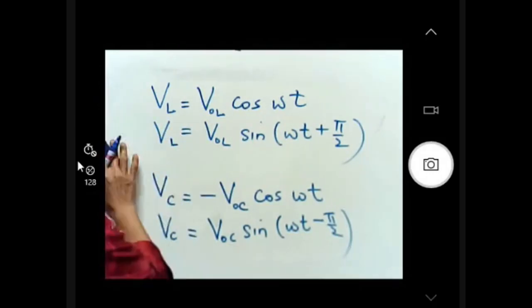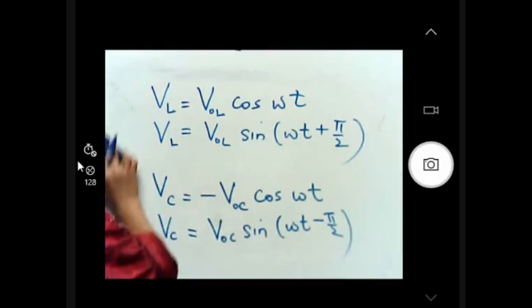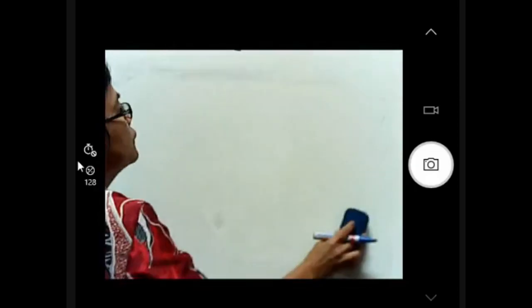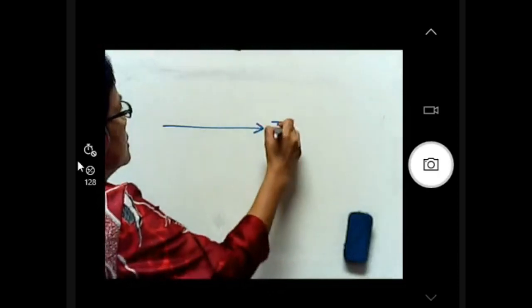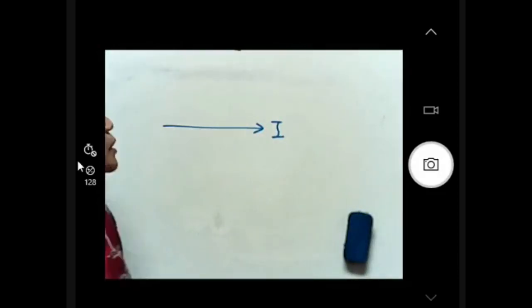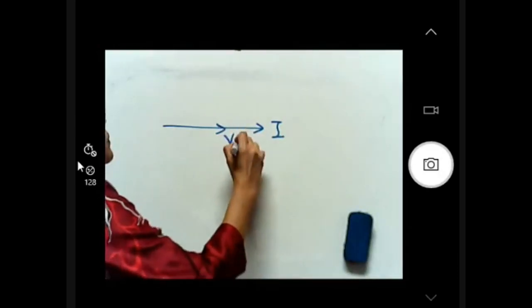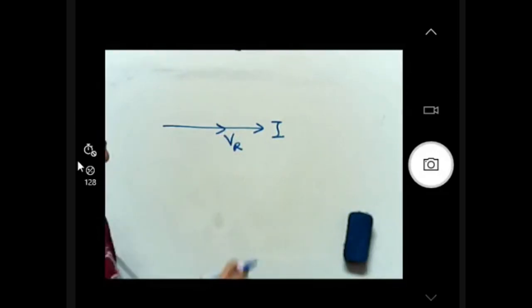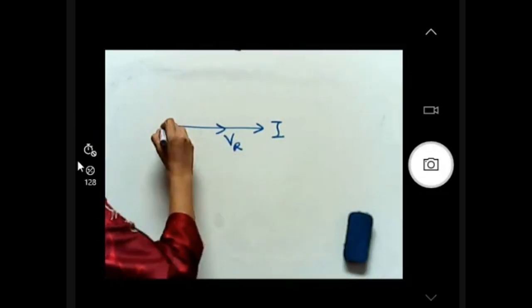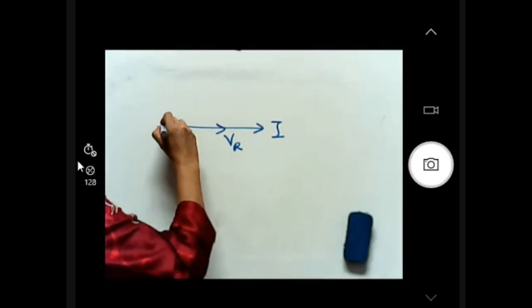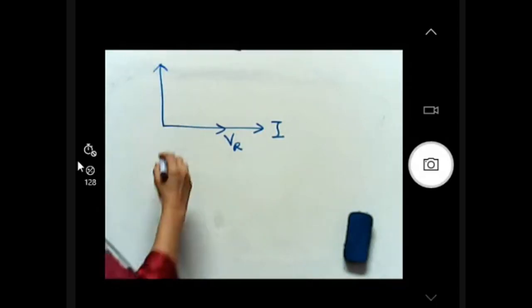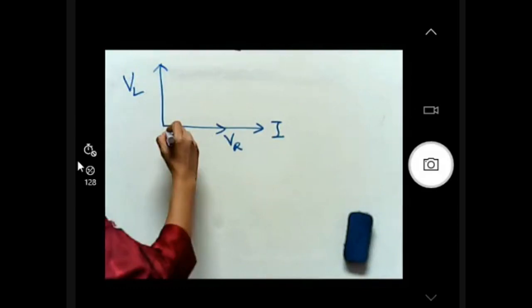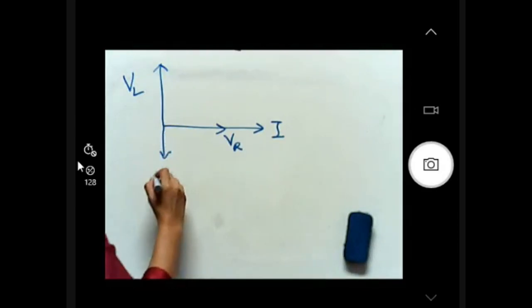Okay, settle. So I don't want to make it so complicated. I'm just going to use the phasor diagram. Meaning for an RCL circuit, if I use current as a reference, my voltage across resistor will sit here. Voltage across inductor, if the voltage is bigger than voltage across capacitor, then I draw this longer. So VL, and this one slightly shorter.